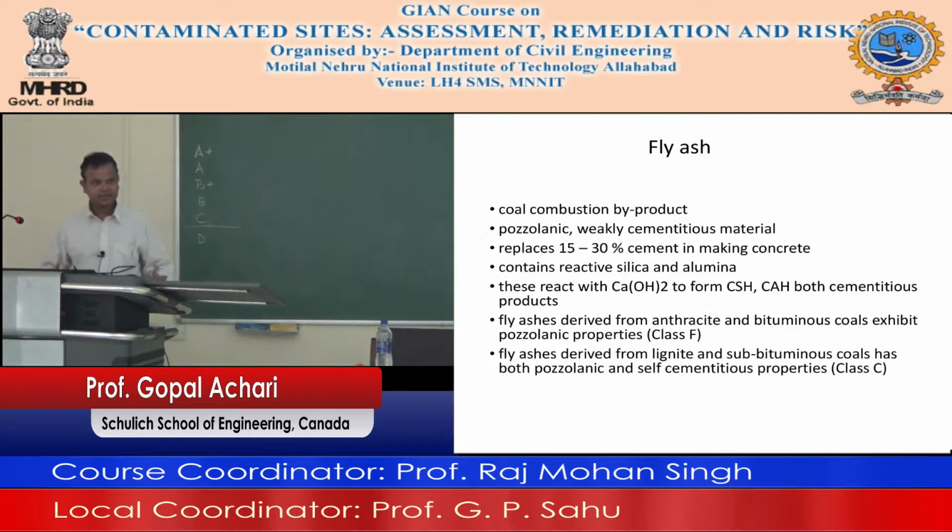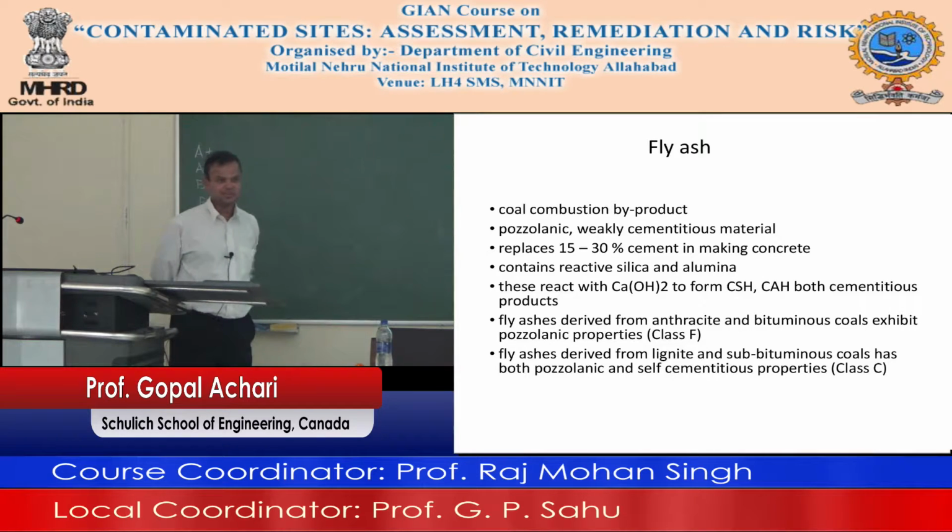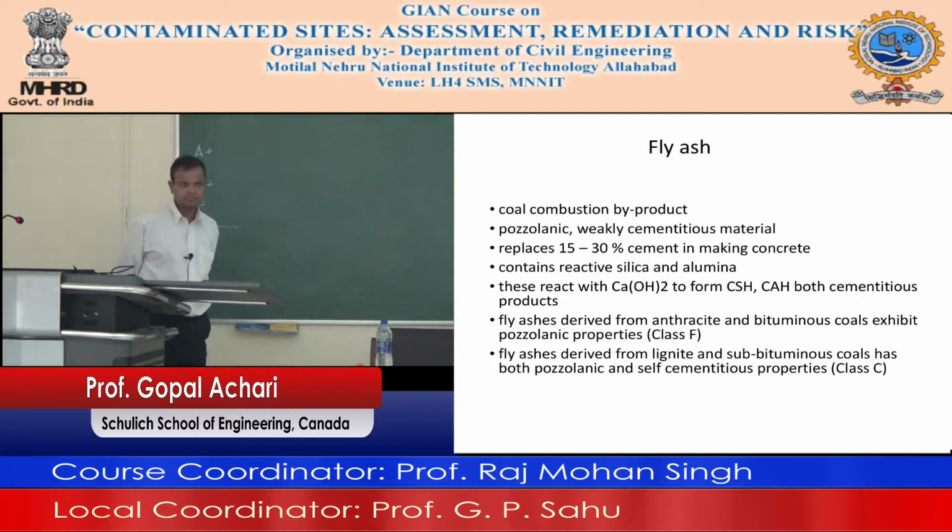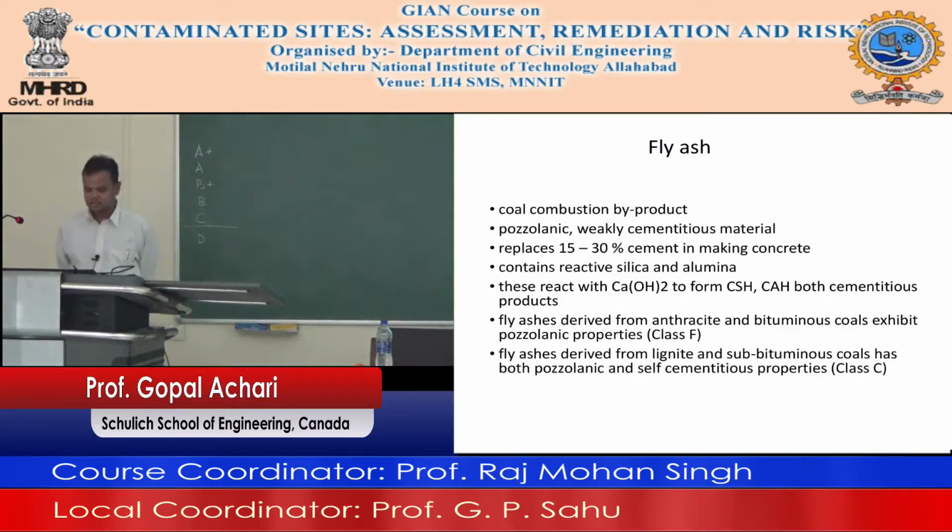So adding some fly ash with cement is beneficial. In fact, much cement actually uses fly ash. A part of the cement is replaced with fly ash in your actual cement, the house construction. It's not 100% cement, it's cement with some fly ash in most cases.